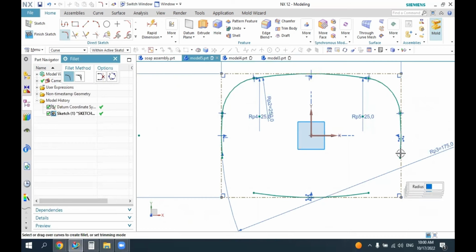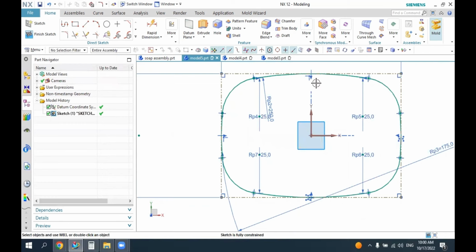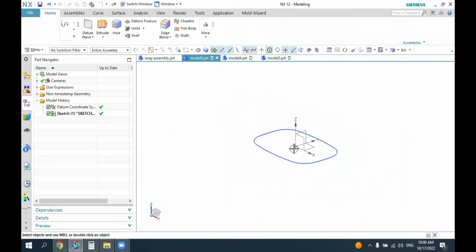since these elements are symmetric, it is disappearing. But you can just select this side and this side. You see it's highlighted in red. Just type in the radius 25. Press enter. The same you see here that this side and this side. You can add the fillet even if there is no sketch between them. So we created this shape. We can finish our sketch.